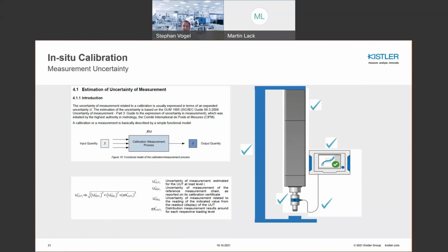The sensors themselves have an uncertainty. The amplifiers for the sensor signal have an uncertainty. And of course, the mechanics add an uncertainty too. So here in the right-hand picture, you see a spindle, a joining system, a linear actuator. And at the bottom in blue, there is the sensor, our Maximus. And this spindle is put on a C-frame.